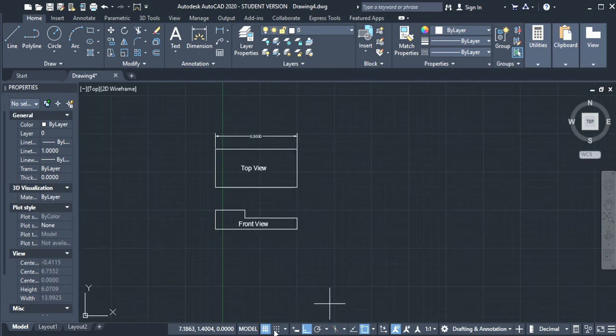Now, if this is on, and I hit dimensions, sometimes, nope, let's see what's going on. There we go. If we turn off the snap cursor to 2D reference points, when we hit dimensions, it's just going to give us the line that we're on. So we can click the line that we're on and move out the dimension we want. That's a little bit easier for this assignment, so we'll go ahead and leave that off.